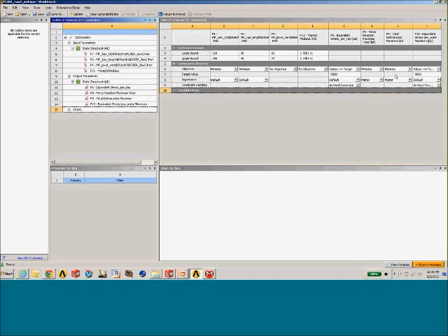So I want to minimize the deformation as well, because that represents slop in the system, which would make my vice grip less valuable to me. So I'm going to specify that I'm minimizing both those quantities and that I have a higher level of importance on those particular parameters. Moving over to our input quantities on the left here, the Young's modulus I really have no control over, so I leave that as no objective. The same with the vertical pivot. I found that had a relatively weak correlation, so we're not going to assign an objective to that quantity. But in the case of the jaw OD and the jaw length, I'd like to make the vice grip as small as possible, because that minimizes the amount of material required and the weight of the tool. So I'm going to try to minimize those as a goal.